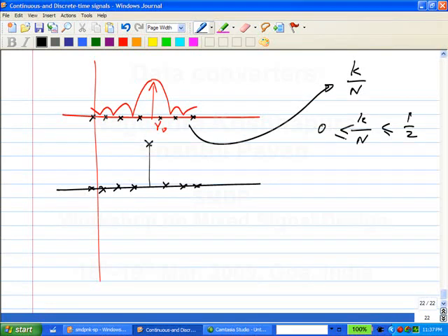Basically, see, if nu naught happened to be one of these points where I am going to calculate the DFT, what will happen? The sinc-like curve will be reproduced here. Okay. Notice that I am taking points at a spacing of 1 by n, and the sinc also has nulls at spacing of 1 by n. Okay.